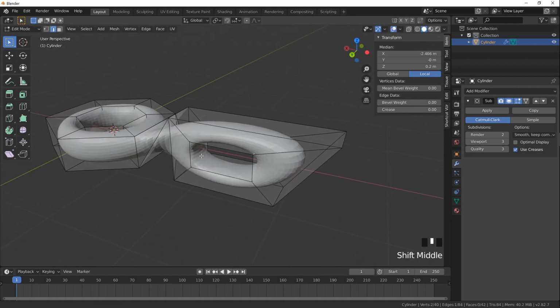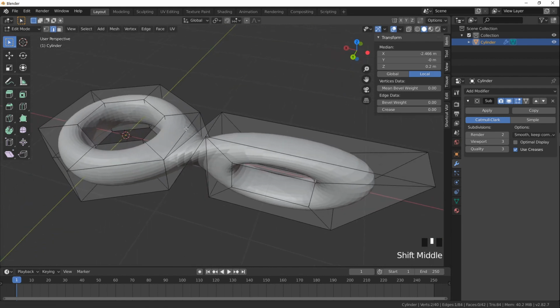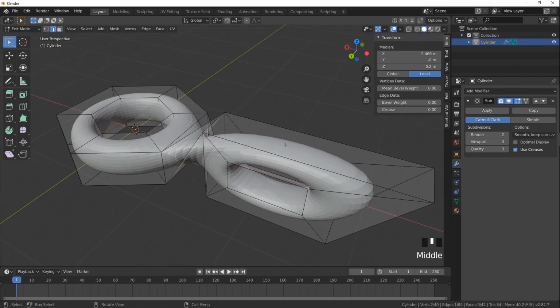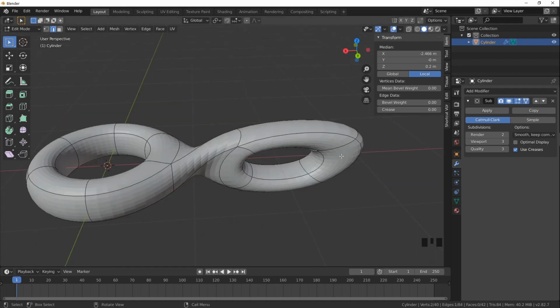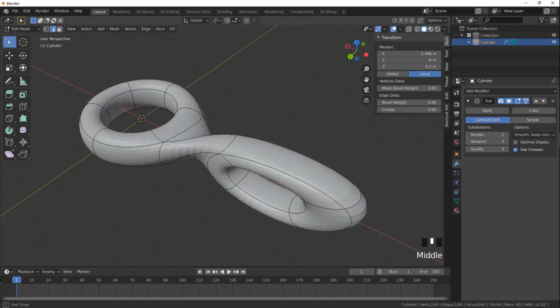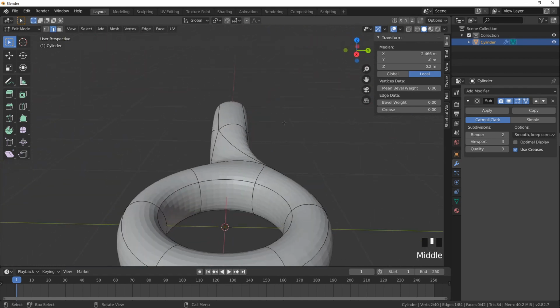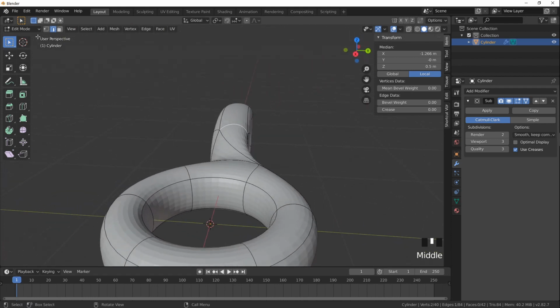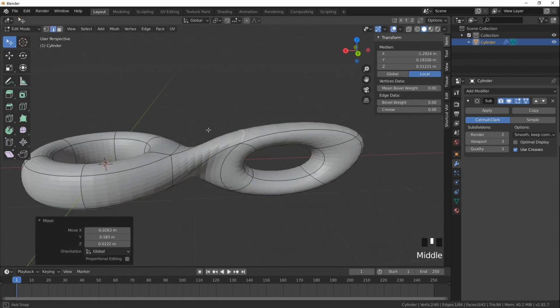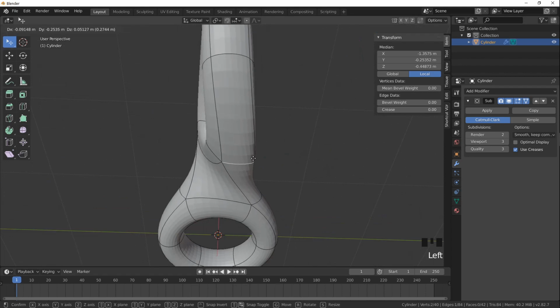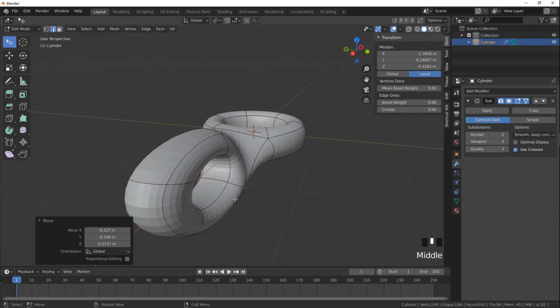And sometimes it's a bit tricky to select all the different parts because there is this gap between the polygonal shape and the subdivided one. For that reason, I usually recommend to use this option that projects the cage on the subdivided surface. Now we can manipulate that shape, trying to make it as nice as possible. For example, we can easily select some edges, and we can use the tweak tool if you want to manually change it and find a shape that you like more.